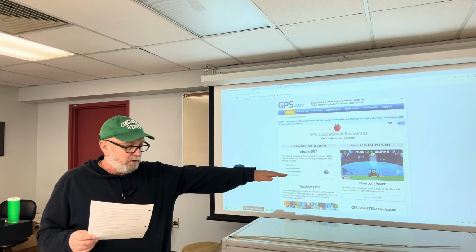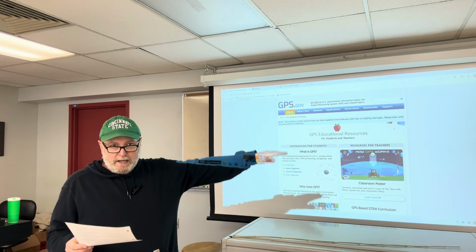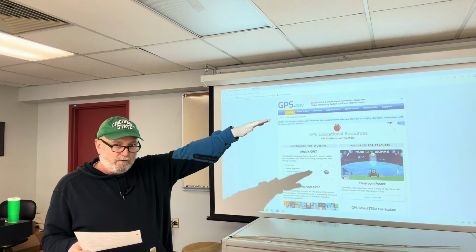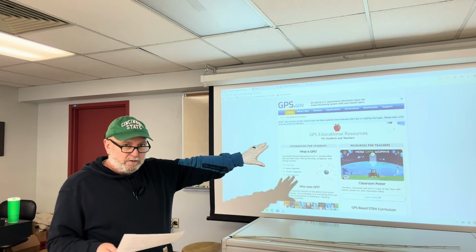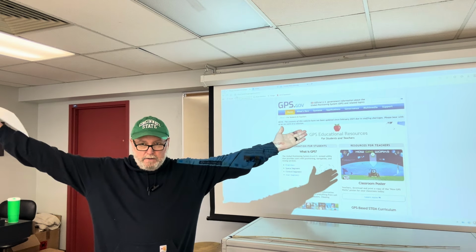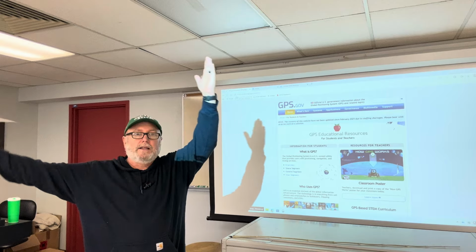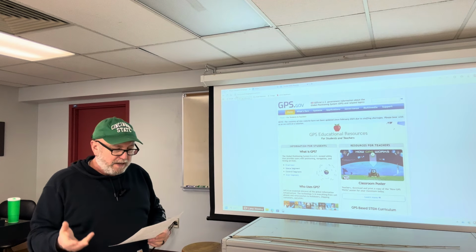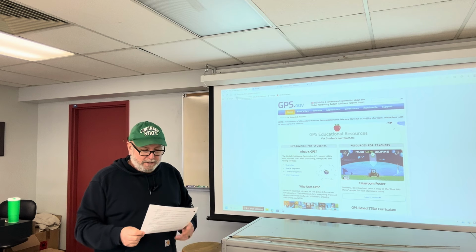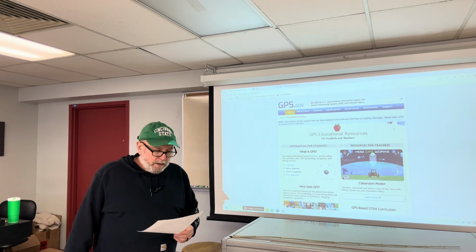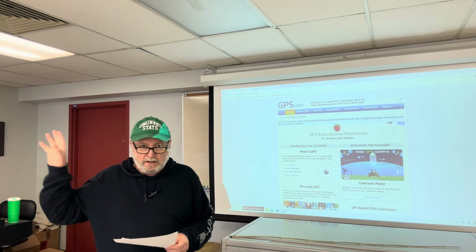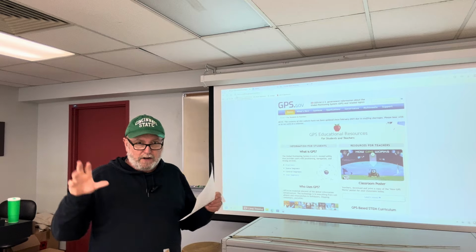So looking at the horizon as 0, we typically have an elevation mask of like 10 to 15 degrees. So anything within that angle from the horizon, we exclude satellites that might fall into that. But anything from 15 degrees overhead back down to 15 degrees or 10 degrees, whatever, is also a good mix of high and moderate elevations. Different azimuths in opposite directions. So are they in the northern sky, southern sky, eastern, western sky? They're not all clustered maybe in the southern portion of the sky.